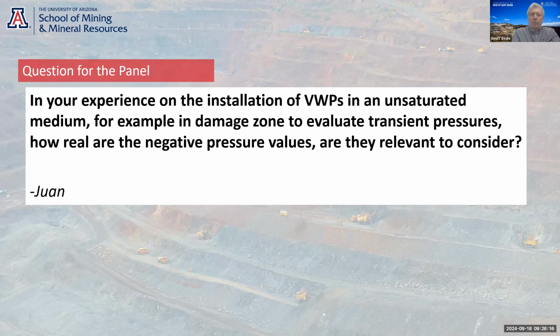It's very, very difficult to measure negative pressure below about 1 atmosphere, below 10 meters, because below 10 meters it's no longer water. It converts to a gas, and the pore space essentially cavitates. So it's very difficult to measure negative pressure in a real-world situation. There's been a lot of work done on that recently, because a couple of mines think they've got strong negative pressures due to hydromechanical coupling. As a group, none of us are very convinced by the data that we see from the tensiometers.